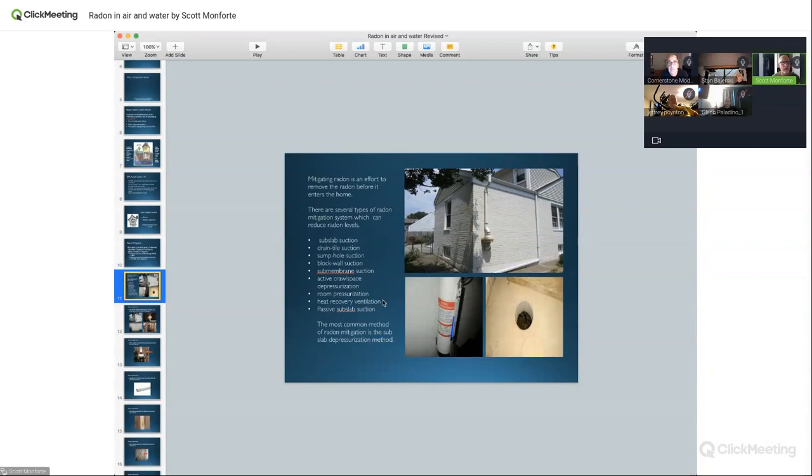interior. They'll say that an interior run inside the building is better than an exterior wall. To me, it makes no sense, but they say, if you have a chimney surrounded by warm walls, it'll draft better. I have a chimney on the outside and it doesn't draft well. My chimney in the center drafts very well. Radon systems up the center. That's why a lot of these new homes, they're running them up the middle, because they feel it'll be better for a passive system.